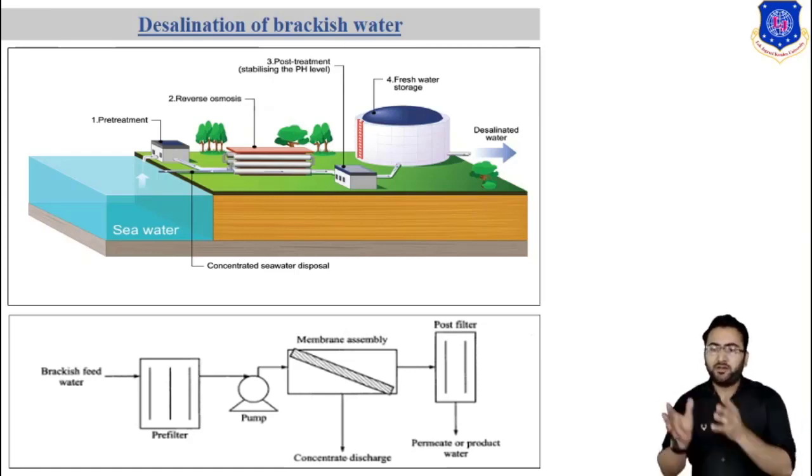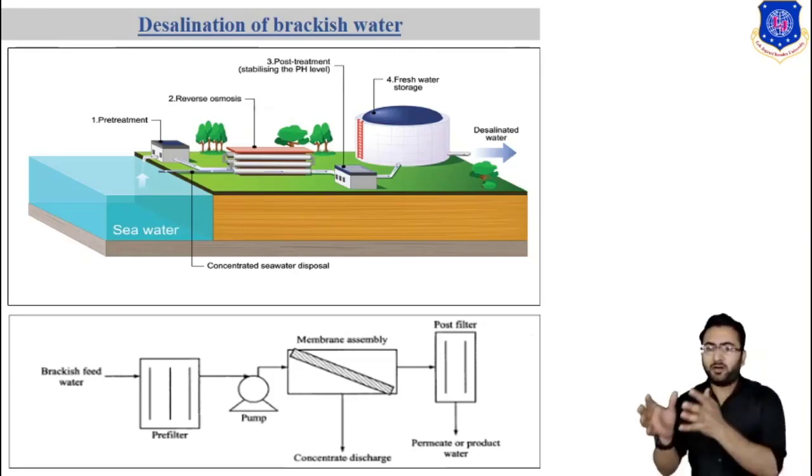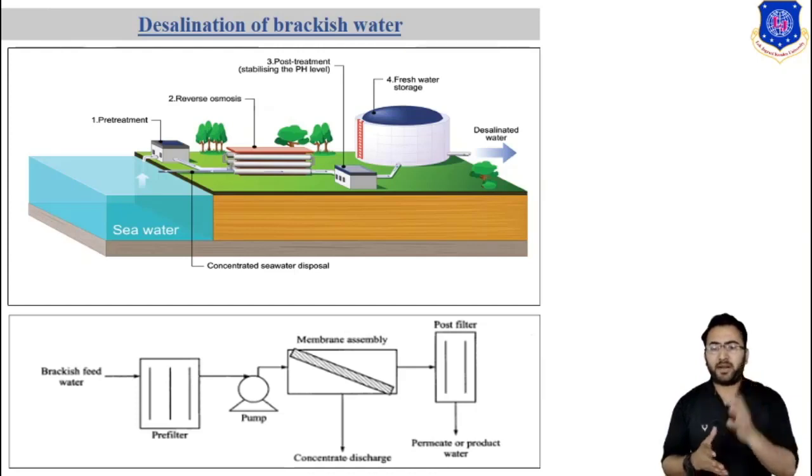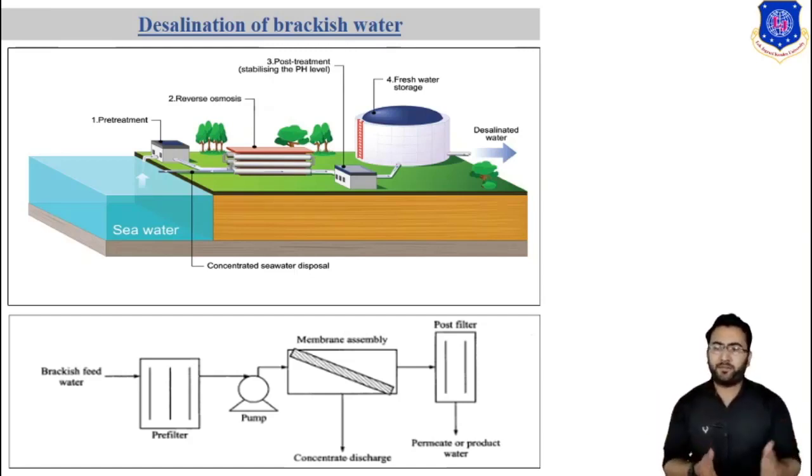As such, solids within the water must be removed, and the water is given treatment to prevent salt precipitation and bacterial growth on the membrane. The pump supplies the pressure needed to push the water through the membrane, while the membrane rejects the passage of salt through it.